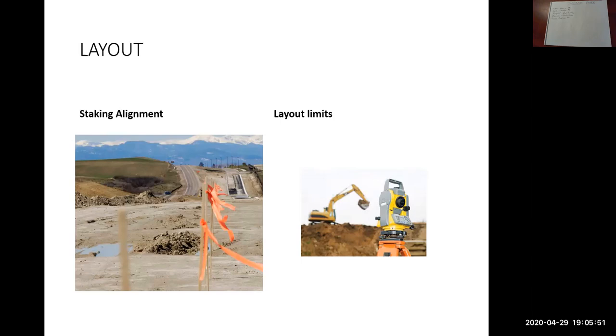Once you put the subbase in, your surveyors will come back out and restake again and show you top of base layer. So it's multiple stages. The surveyors don't just come out and lay out the entire project in one go and then go away. They're constantly coming back.